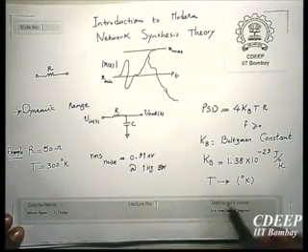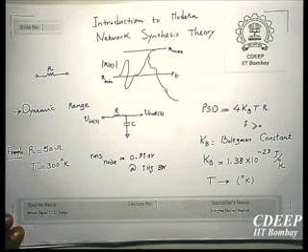Okay, because this is power spectral density, and from noise background that you have already, you know that if it is white, then it's very easy to calculate RMS value, because you need just to take the integral of area for a 1 Hertz bandwidth, and because noise density is constant, therefore it will be same as PSD at 1 Hertz bandwidth.